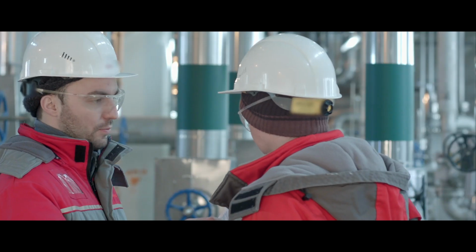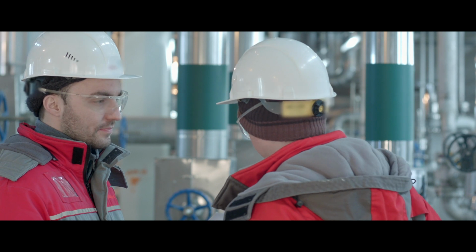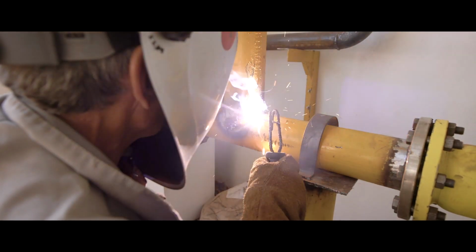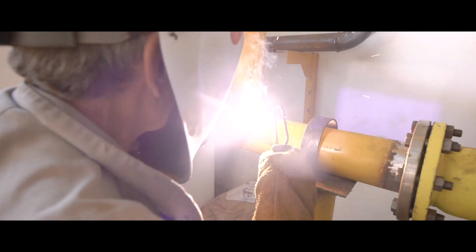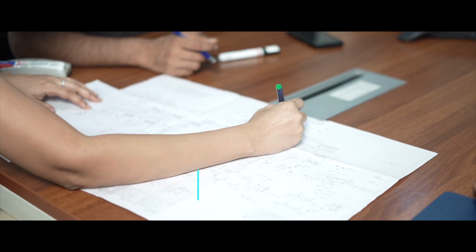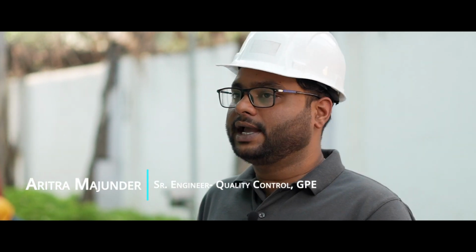The skid hookup starts right from the minute we start planning the skids. The skids are designed in such a way that any interconnection should be done from skid to skid, and they're well planned for easy assembly at site, and all the interconnecting piping has to be delivered accordingly in not fully welded condition so that at site they are installed and then welded accordingly. For the pipe spool, we are marking an IPTP point with reference to the P&ID to ensure there will be a smooth commissioning activity at our client's place.